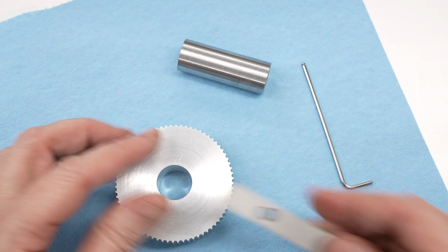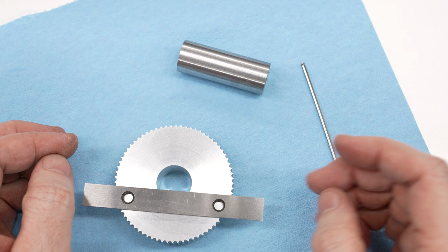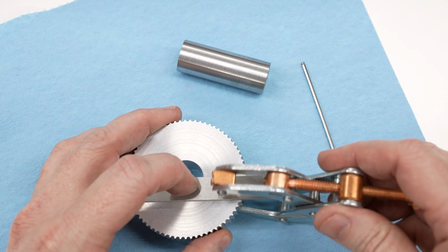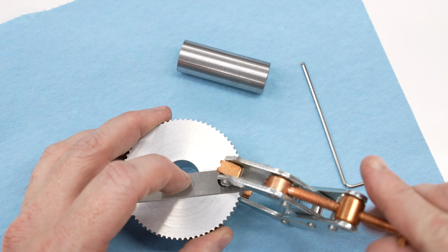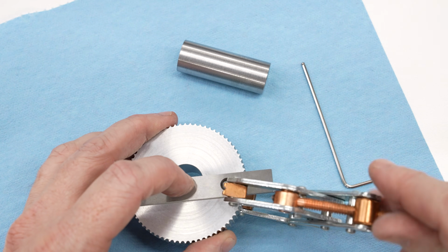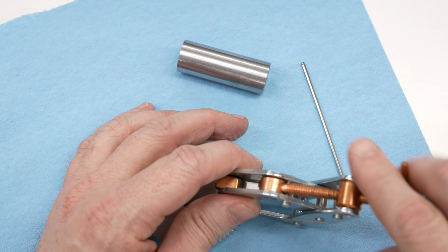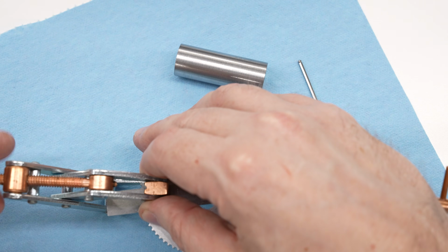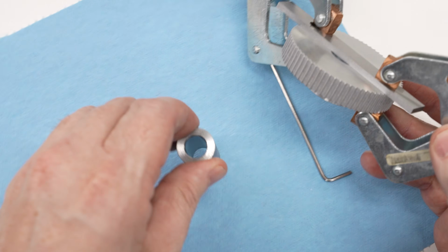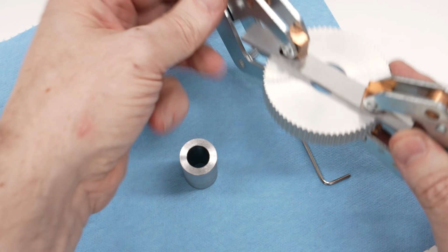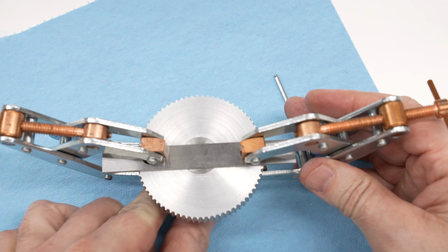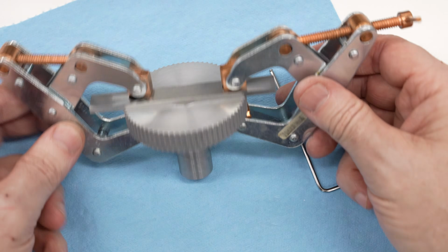Now I want this to be lined up with the face of the pulley, so I'm going to clamp on a small parallel just to make it easy to line up so I don't have to do any measuring and I don't have to do any adjusting. And I'll just clamp this on with a couple of can't twist clamps, which has the added advantage of adding comedy to the YouTube video. I don't know if you've ever tried to handle one of these one-handed, but it can be pretty challenging. Okay, with those on, slide that down, make sure that registers, and it does.